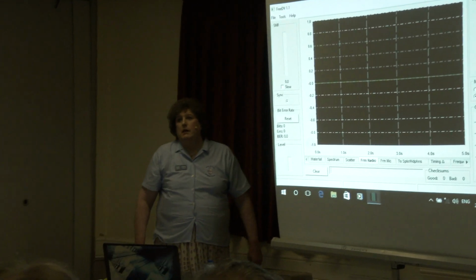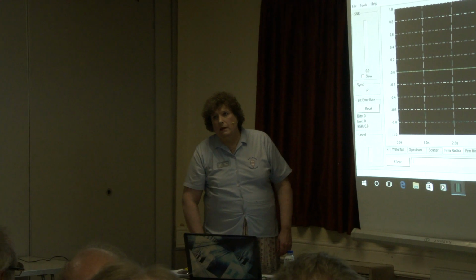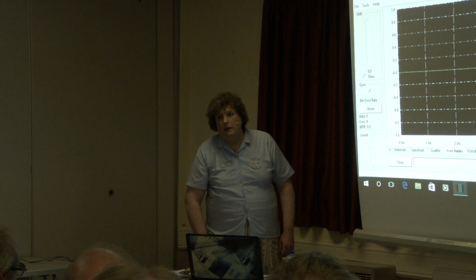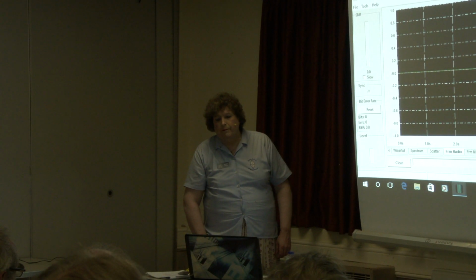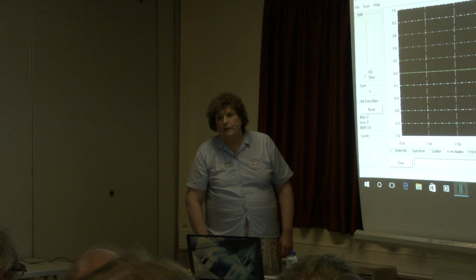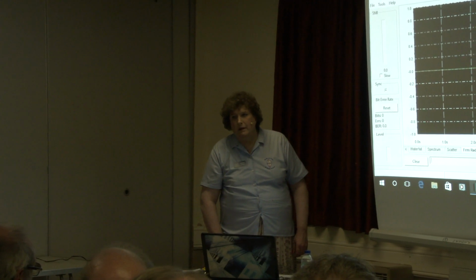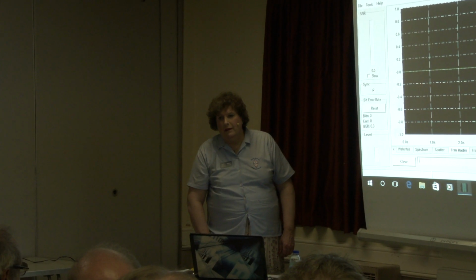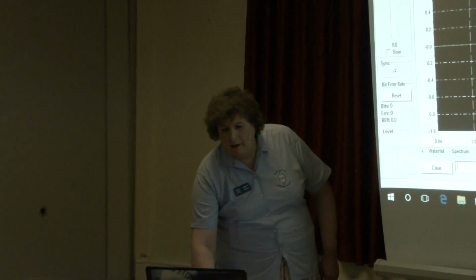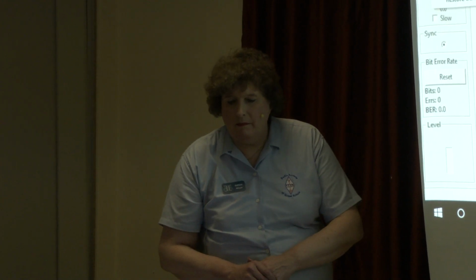The other thing I noticed, and I don't know if you have the same thing with your software, is that when you transmit, for example with WSJT, you can ask it to go into what's called split mode, which means it only uses audio in the range 1.5 to 2 kilohertz. So the second and third audio harmonics are outside of the passband of the rig and therefore aren't transmitted as RF. You see a lot of people who don't do that, and you can actually see them wiping out all of the harmonics from their audio if it's overdriven.